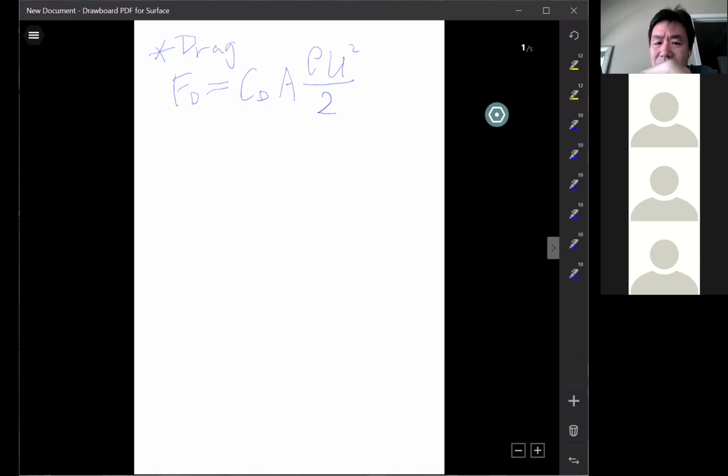In the race car industry, the same equation is also used to calculate the drag force. Or in airplane design, you need to calculate the drag, same thing, okay? So that's the equation. Drag coefficient is one thing people look at to see if the drag is big or small, okay? The drag coefficient is a dimensionless coefficient. If you multiply half rho u squared times the frontal area, then it becomes the drag force. Okay, so let me send you two figures in the textbook, 6.9 and 6.10. I texted you in the group message. I have the picture copied here. This is 6.9 first.